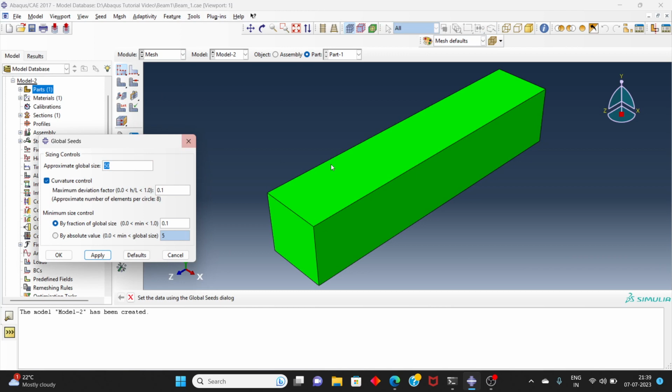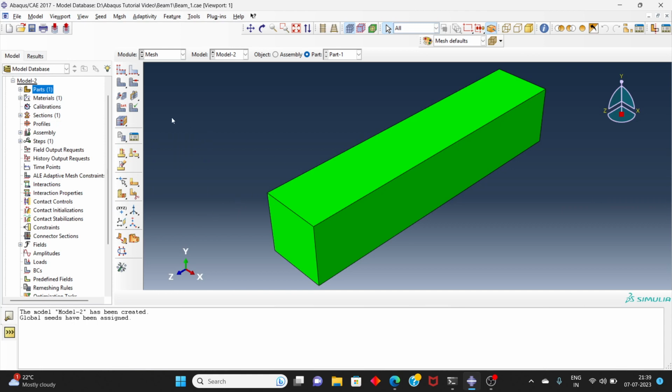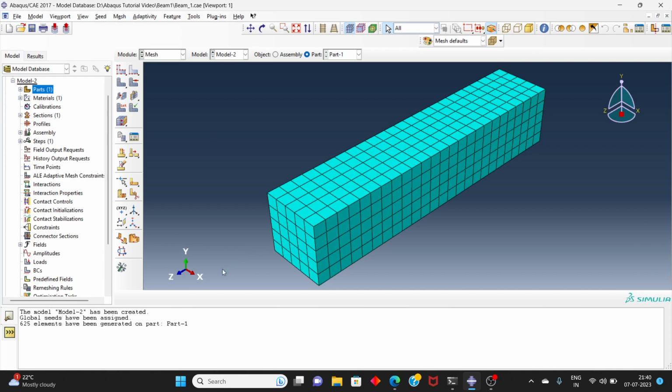Here, one thing I want you to observe is this green color. This means your meshing will be structured meshing. If you don't get this, you can either get yellow color or pink color. Pink color would mean you will get tetrahedral meshing. Yellow color could be a combination, structured or unstructured, something of that sort. Somewhere you will get tetra, somewhere you will get quad elements.